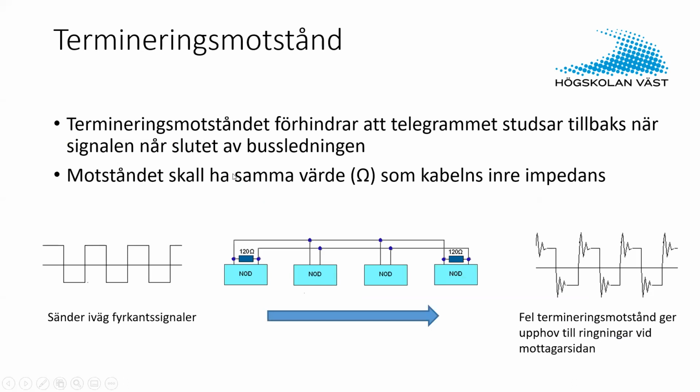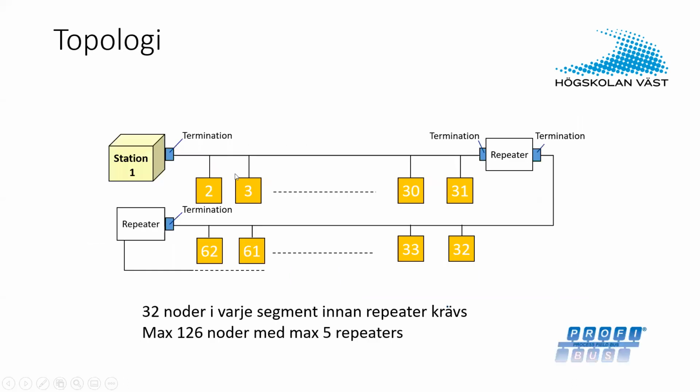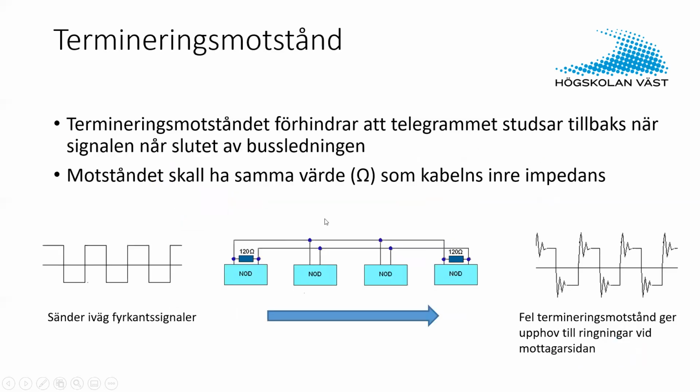One thing that is a little bit interesting is that it says termination here on many different things. It's a very special thing when you have long buses and long wires. You typically need a termination resistor, and that's very common for bus wires in many different buses.